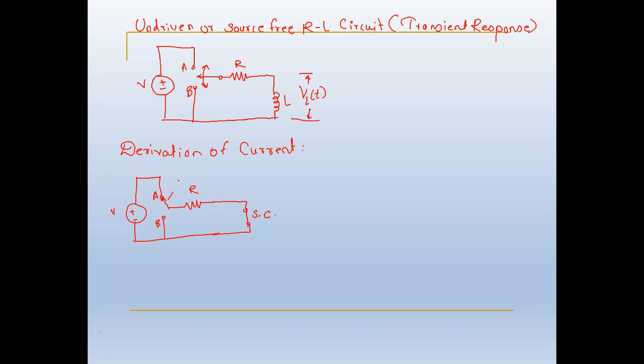The switch is closed for a long time. So at that time what will happen? When the switch is closed for a long time, this circuit will be in the steady state, and as it is the steady state, the inductor acts as a short circuit.